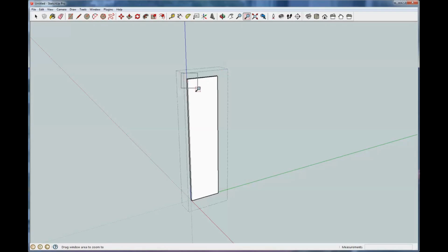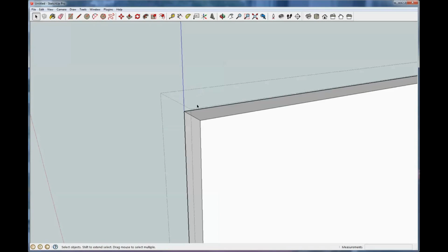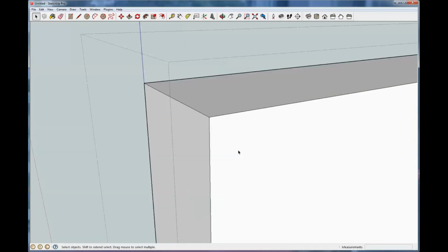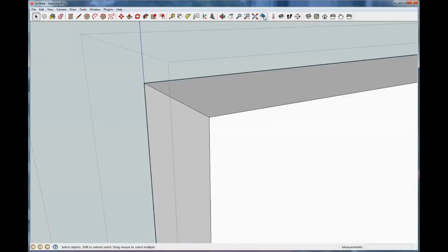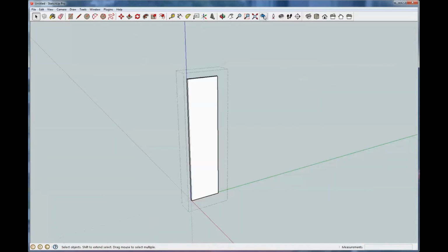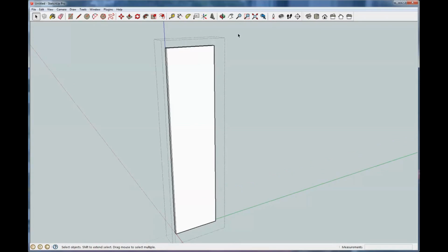If we click a box and drag it, it'll zoom in to that corner. The next one is zoom extents, which takes it clear out. Whatever is in your model, that will take you out to see the extents of your model. This previous one backs up. You can click it several times and it will show all your different zooms. I don't really use that a lot. I find once I have the third mouse button, I don't really use any of these.